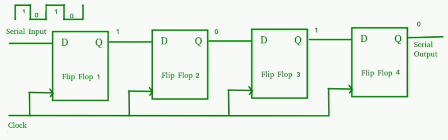DACs and ADCs, digital to analog converters. Specification of DAC: the resolution of a DAC is the change in analog voltage corresponding to an LSB increment at the input. Resolution equals VR by (2^n − 1), where VR is the reference voltage corresponding to logic 1 and n is the number of bits. Analog output voltage equals resolution times the decimal equivalent of the binary data.